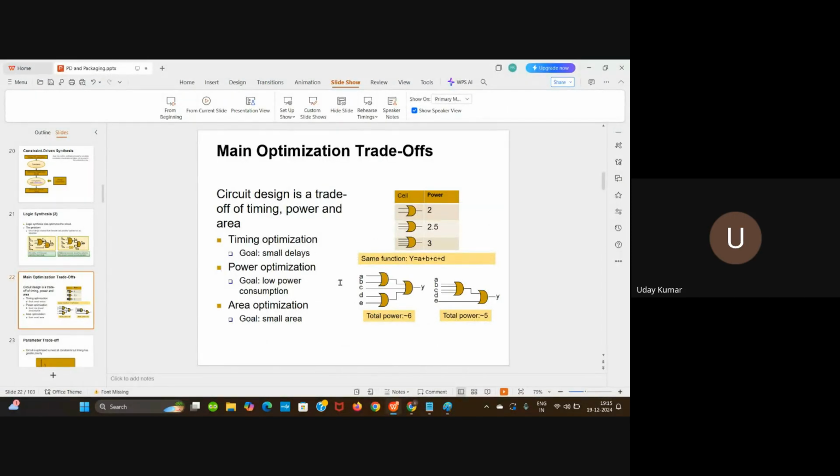In the same similar fashion, the power tables will also be there, and this tool will intelligently decide what type of gates should be used, like three fan in or 4 fan in, to reduce the power. And similarly the area. The tool is intelligent enough. It checks the logic there.